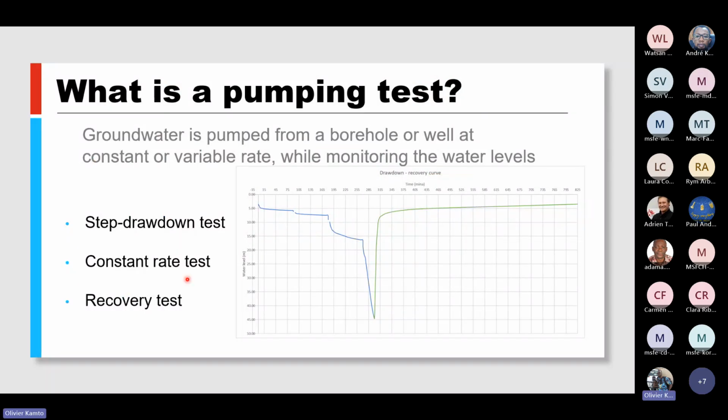So I was explaining a while ago, during the pumping test, during the step, there is the characteristic drawdown curve, which should look something similar to this, where there is a very sharp drop at the start of the pumping event and it gradually stabilizes at the end of the pumping event.